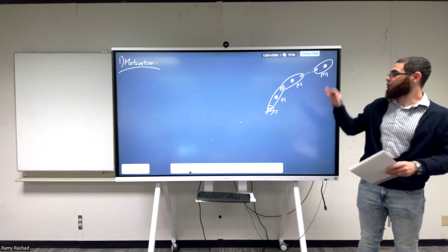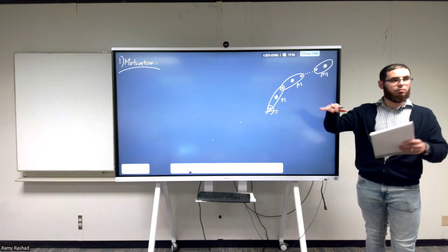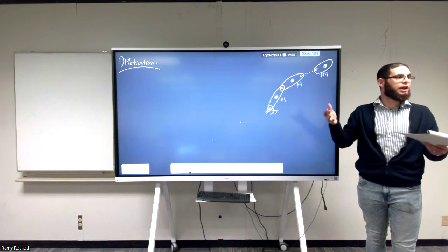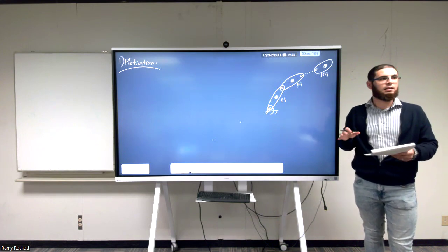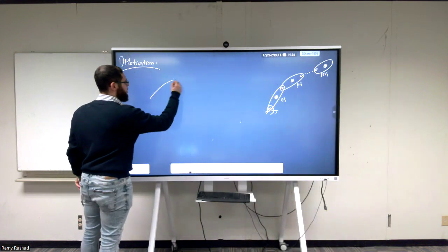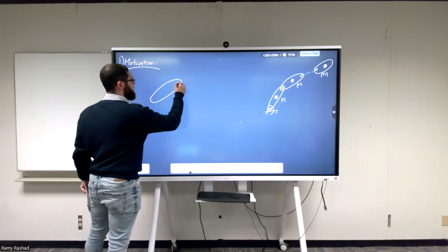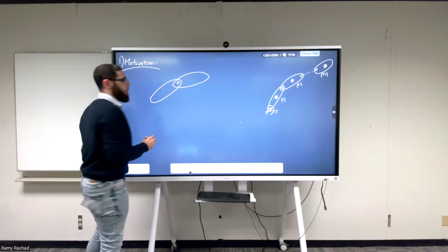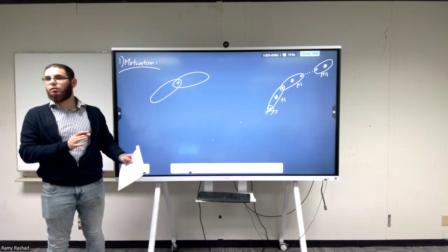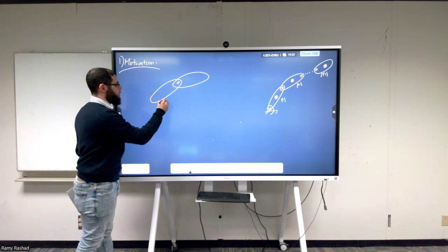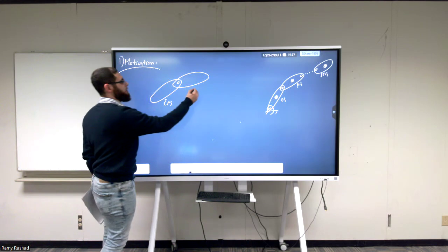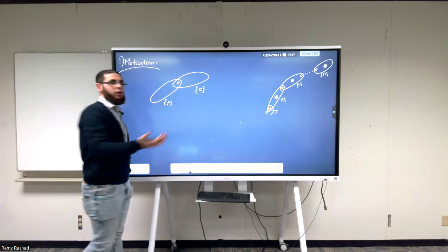What we're going to be doing here is that what you can see as this multi-link robot, or this open chain serial linkage, we can boil it down to understanding the relation between one rigid body connected to another rigid body by one revolute joint, right? In the end, it all boils down to having one parent link and relating it to another link, which we're going to call the child.